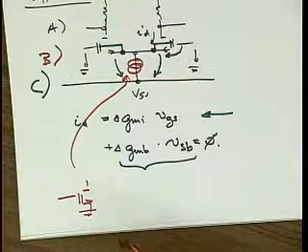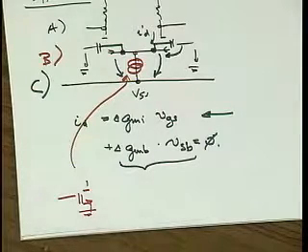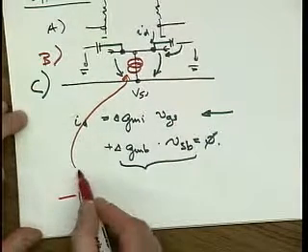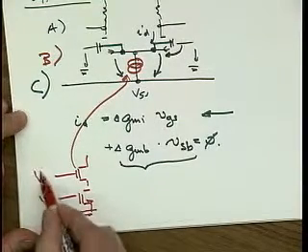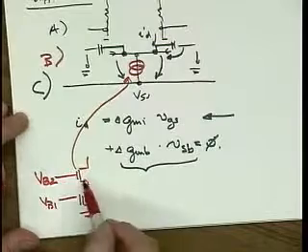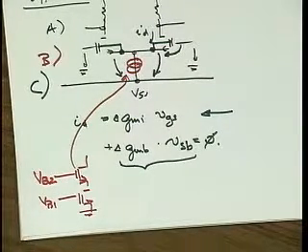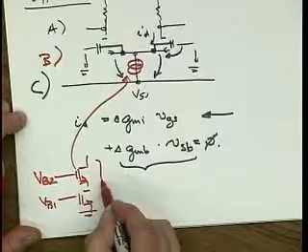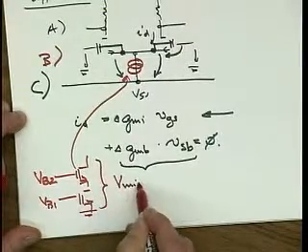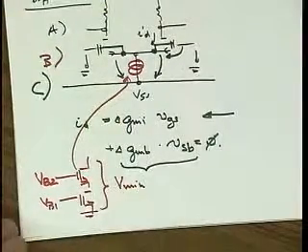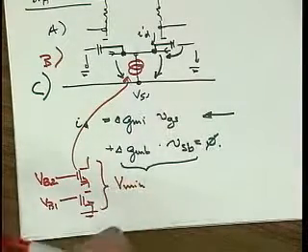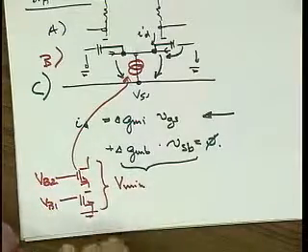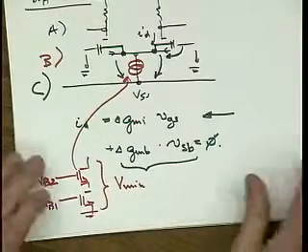But again, the common mode rejection ratio is not going to be that fantastic, maybe 60 dB or so at low frequency. So a way to get around that is, so that would be a V bias 1, V bias 2, is to put a cascode. Now the common mode rejection ratio goes way up, but it looks like, well, gee, now I paid a lot of voltage headroom just in making this current source. So it's not a freebie, right? It costs something, but on the other hand, it's maybe well invested millivolts.